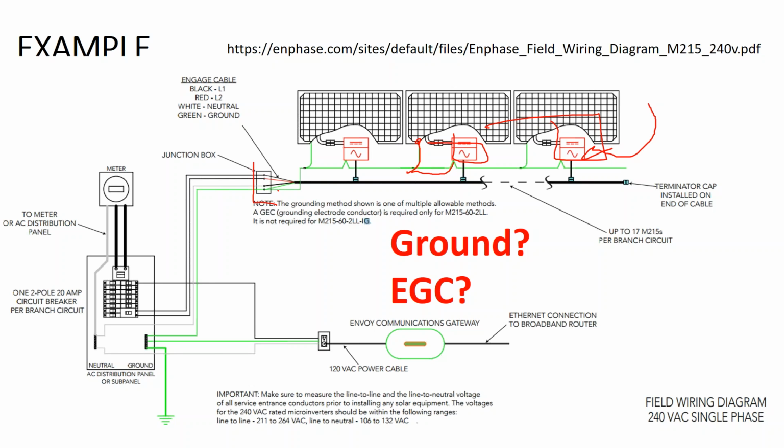So what happens if I have a plastic box instead of a metal box? Well, the plastic doesn't need to be connected to ground, but you still have to carry that grounded connection through the box. So how do you get there? Do I connect to the side of the box and carry that connection through the side of the box? Well, you can only do that with a metal box and not a plastic box. And so then you get into the fittings that go into that box: do I need to use a grounded fitting that grounds to a ground bar across the plastic box and then ground the next fitting onto that ground bar to carry the connection across? Or do I just use a metal box and have the fitting be listed to ground directly to the metal box?